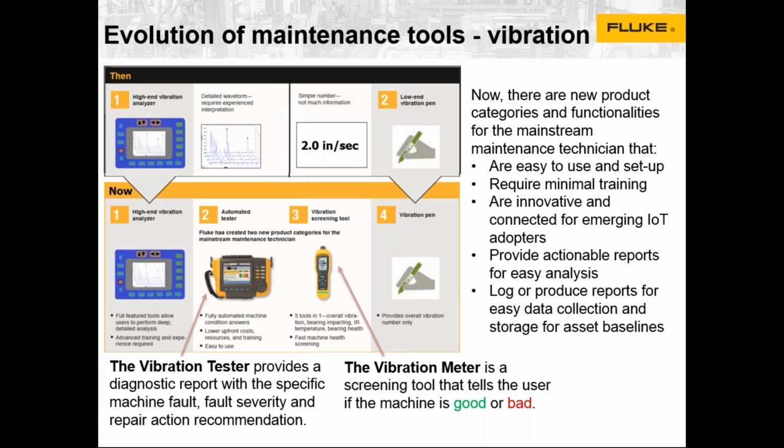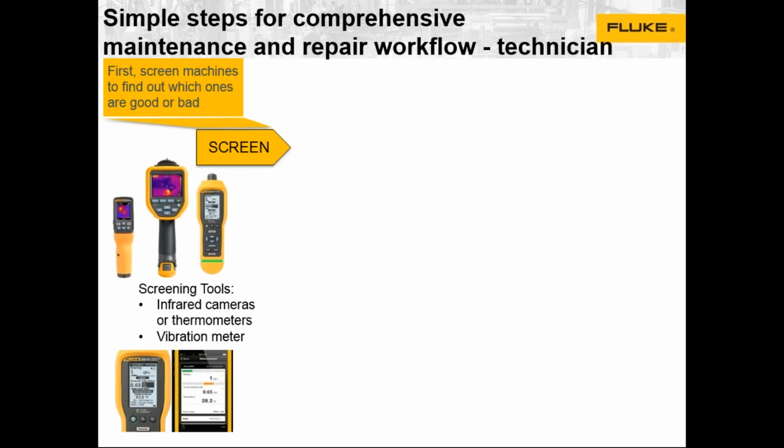So if we think about it, this is the nurse and the doctor that the medical industry has. So instead of trying to attack all your problems with just a high-end specialist, let's use 3 different levels. The vibration meter to see if it's good or bad, the vibration tester to find the most common faults and tell us how bad it is and when to fix it, and then bump up the faults when needed to the vibration expert with the analyzer.